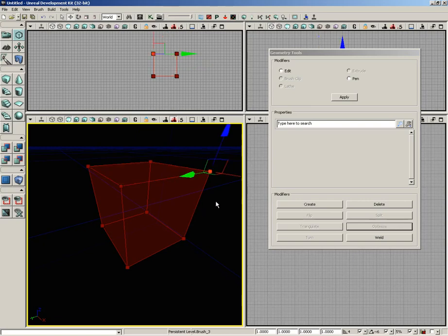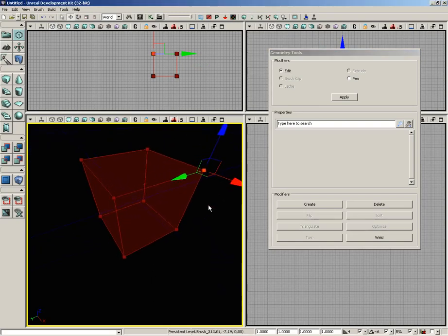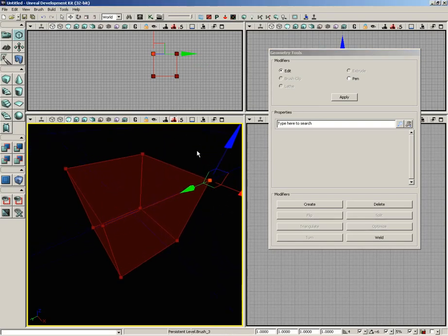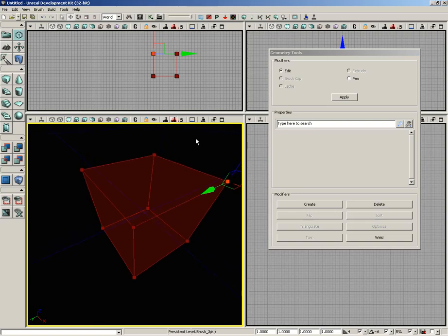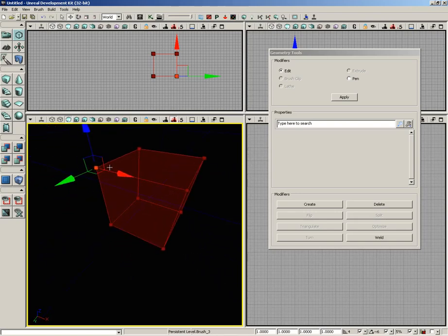All right. Now, with that understood, let's take a quick look at edit mode. Geometry mode's edit mode. That's what I meant to say. Which is pretty easy. It's just a straightforward mode that allows you to manipulate components. As I mentioned, we get the ability to more easily select components, such as polygon faces and vertices. And what can we do with them? We can move them and we can scale them. We cannot rotate individual components, though you can use a component selection as a means to rotate about a pivot. But let's just take a look.